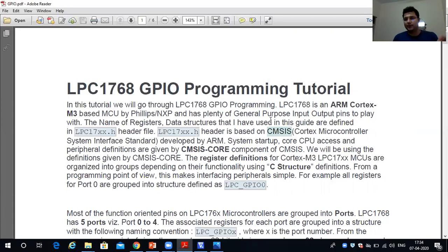Because later on, whatever we write in C, we'll make a hex file out of it, and then that we will embed in our kit. We will load that into our kit ROM, and then that functionality will find its hardware reflection. That's why it is embedded C.